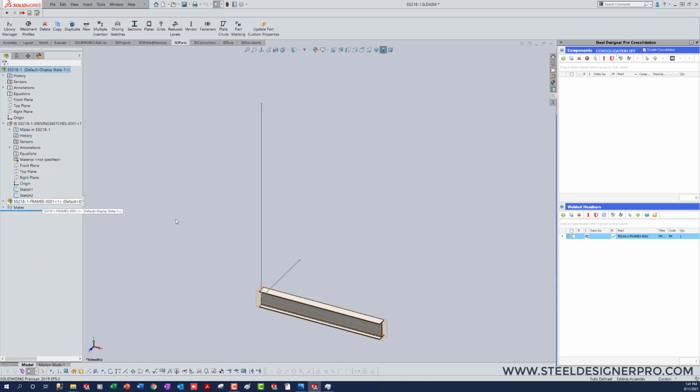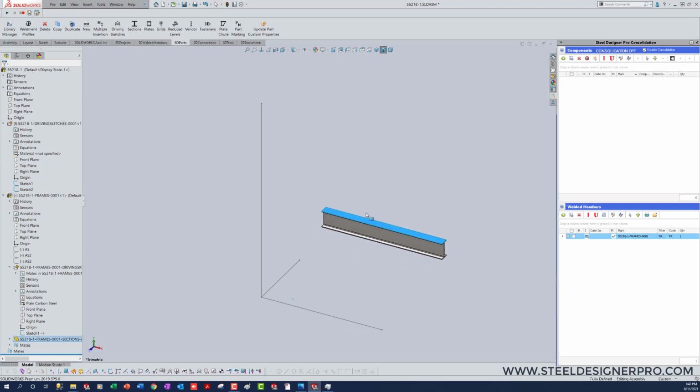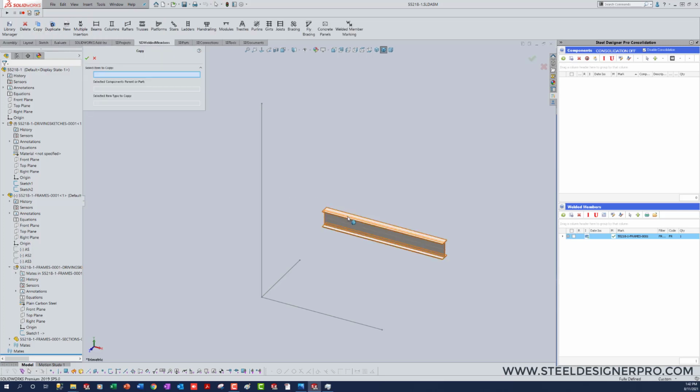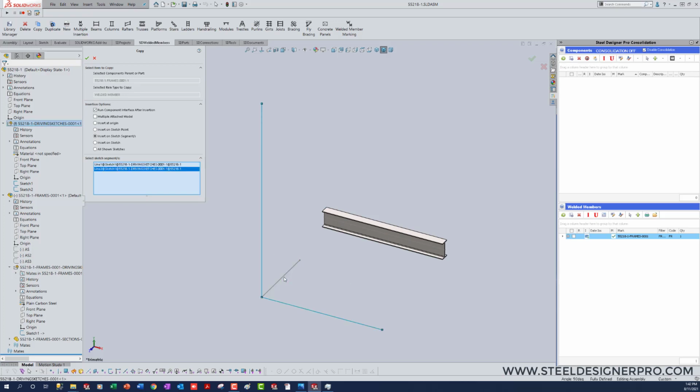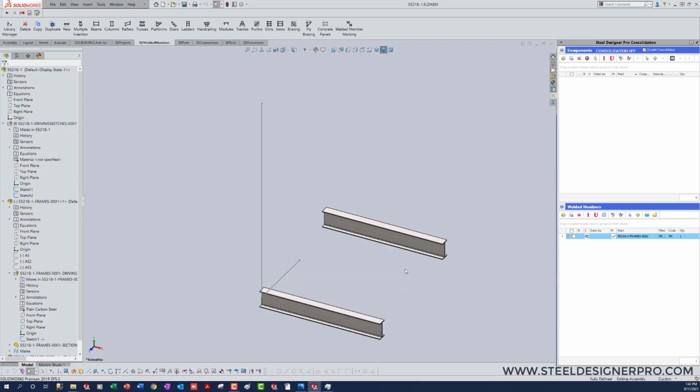So now I have this frame that's no longer attached to anything, but it has 3 attachment sketches in it. So now we'll take and copy that frame to attachment sketches 1, 2, and 3, and this has to be a multiple attached model. There has to be a body in there for you to do the copy. Has to have something to grab.